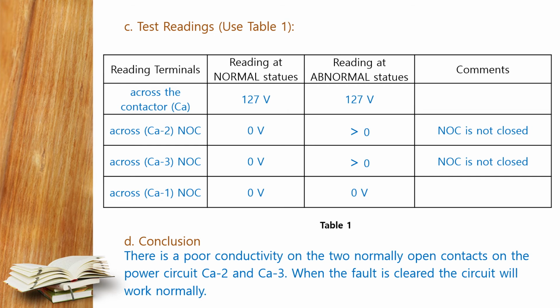Let us take one more reading just to make sure that the contactor is energized, across the holding contact. I'm sure it will be 0, not just should be, because we can operate the high speed mode, and we cannot operate it unless the medium speed mode is running. And to have it running, the holding contact should be with us, because we just pressed and we are not keeping pressing the push button. Across that contact, we come practically and find it 0. It means that the contactor is energized.